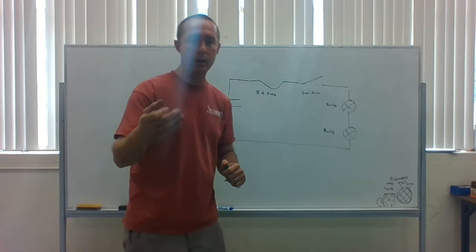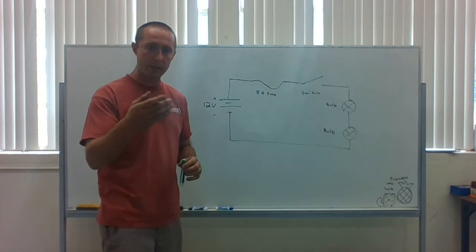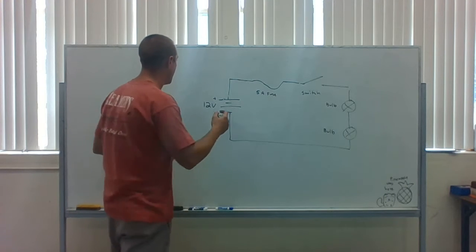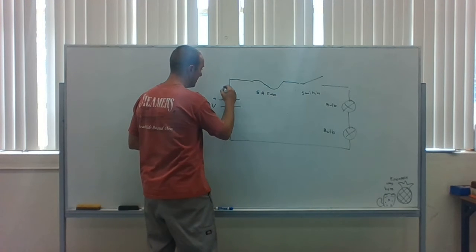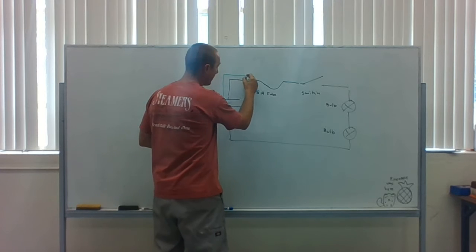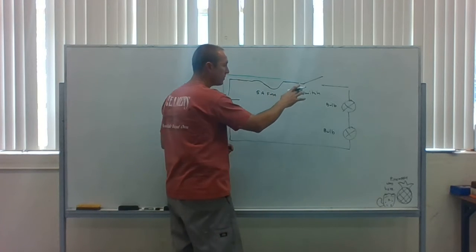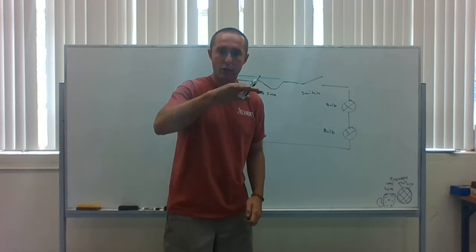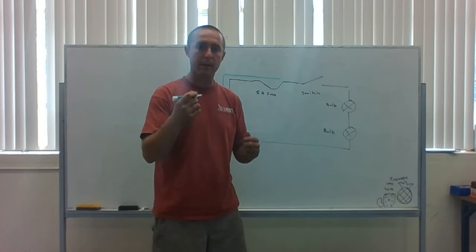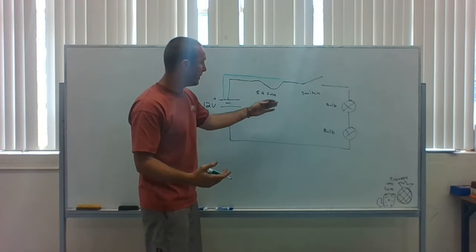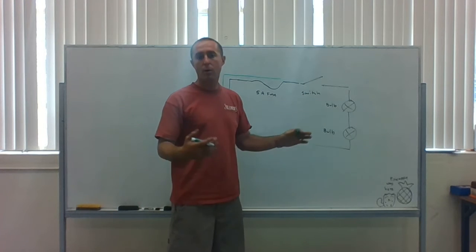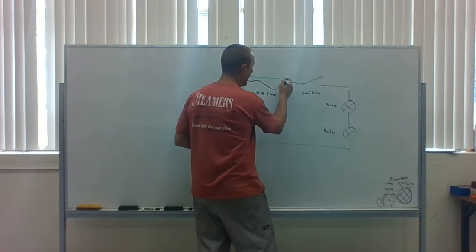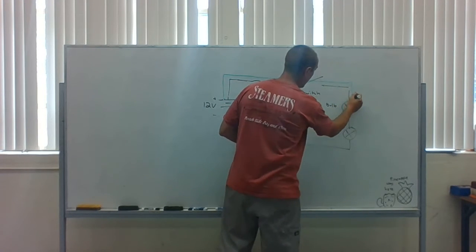But when we're troubleshooting the circuitry, we're going to refer to three different areas of our circuit path. We're going to have the power, which is from our battery going through any fuses, switches, anything that's not consuming current. It's just passing through stuff. And there are safety features there like the fuse. There's control like a switch or other aspects that we might come across. So this would be the power supply of our circuit.